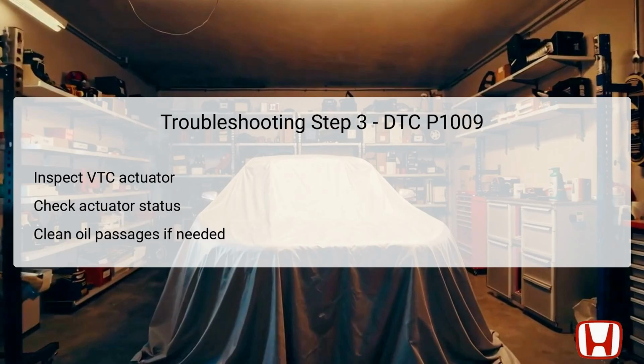If the actuator appears to be in good working condition, proceed to check the VTC system's oil passages, as blockages can impede its operation. If any passages are found to be obstructed, they should be cleaned to ensure free flow of oil, which is essential for proper actuator function. However, if the actuator shows signs of failure during the inspection, replacing it becomes necessary to restore full operation of the VTC system and clear the DTC.